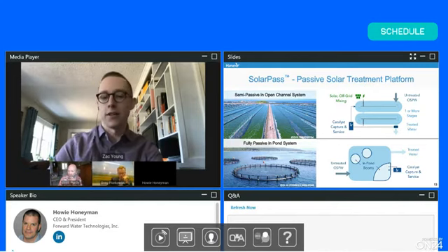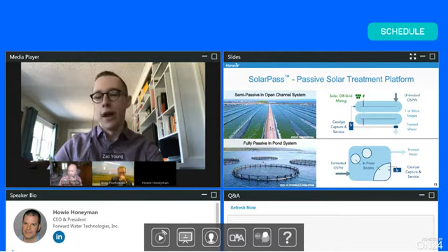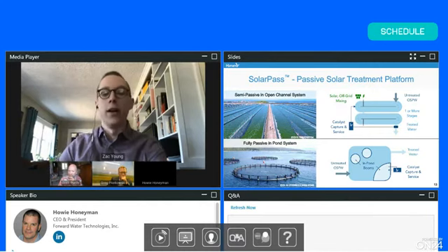In this case, a study on OSPW, as well as being able to deploy that into existing holding systems, where we could do an in-situ treatment of the whole water body, or a continuous maintenance of that water quality through processes using in-pond containment booms and structures that would be able to deploy the material, conduct treatment over a season, and be able to recover and service that using our processes.